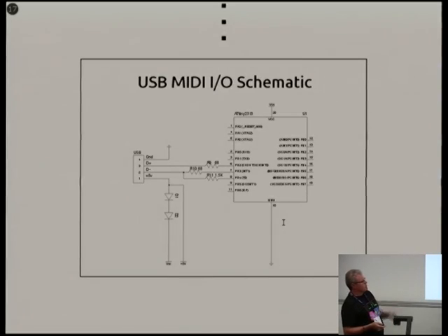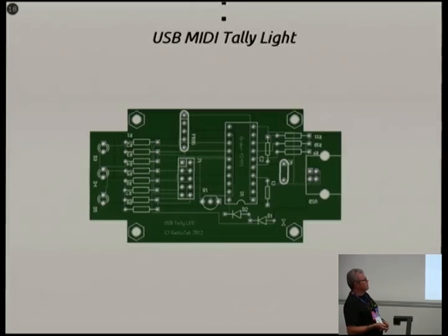You've got 3 GPIO pins on your microcontroller. That's all you need to dedicate to it. At a very low level, I think you can run it at about 6 megahertz. So it's low power, low speed, and you can run a USB 1 type device off it and do everything in software. Even the 5 volt, you just use a couple of diodes to get it down to 3. So really basic, and then everything's a software solution from there on.